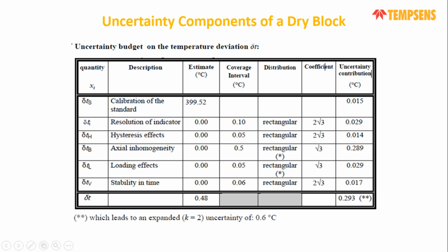Let's say I am calibrating my thermocouples, platinum-rhodium type thermocouples, at 1200 degrees centigrade using a dry block temperature calibrator. Let's say it is our Calsys 1200, which has a temperature range of 250 degrees to 1200 degrees centigrade. So how will I calculate?